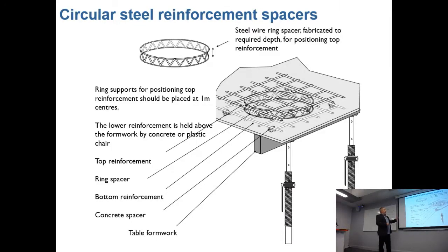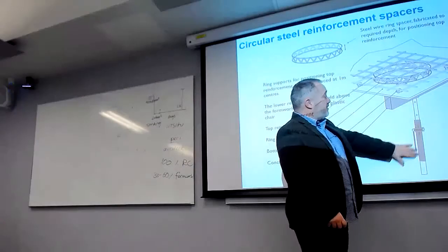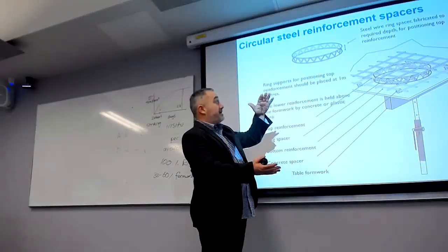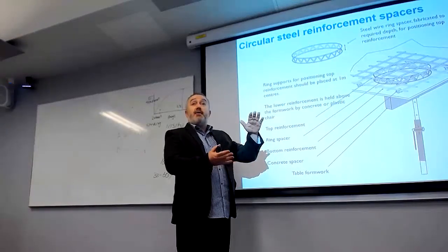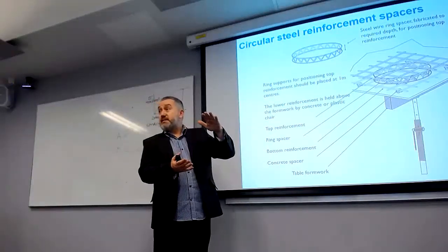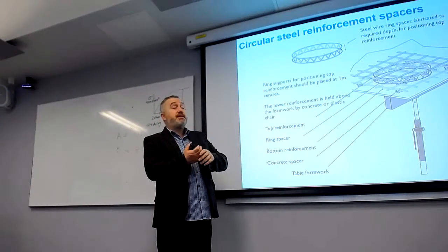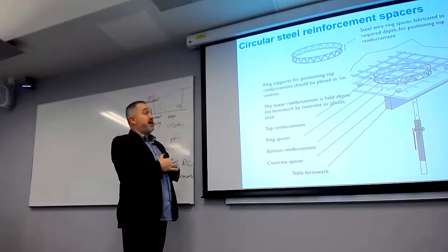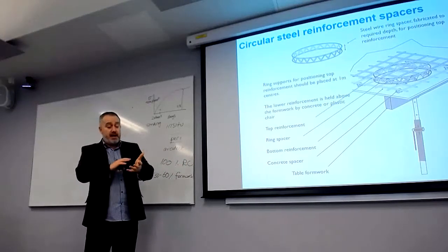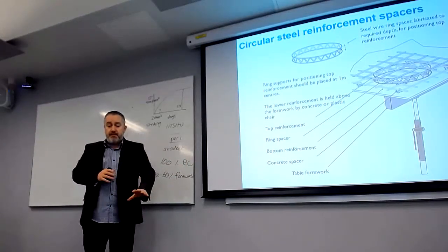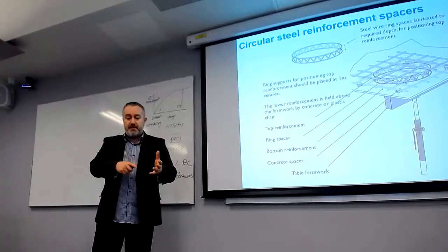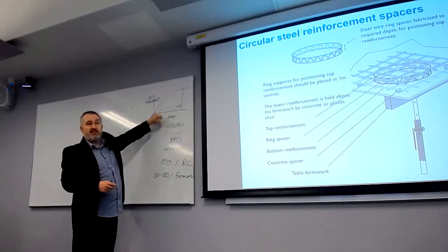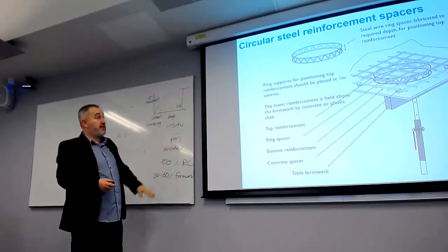So the formwork, again, false work, your beams, and then you've got your pieces of timber that your concrete is resting upon. Now, concrete sticks to the timber, right? It just soaks into the timber surface. So when you pull the concrete off, you can pull off the top surface, and you can repair it. They've got these Hessian bags with little steel parts in, and they put some concrete in and rub it. They call it bagging, to repair the surface of the concrete.